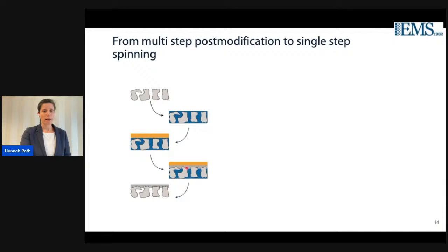These two then react at the interface, and a composite structure is the outcome, where, as said, the porous structure gives the support, and the thin film on top gives the good separation characteristics. And of course, the benefit of this system is that you can combine two different materials which have their strengths on either side. But on the other hand, this makes the production process very elaborate.